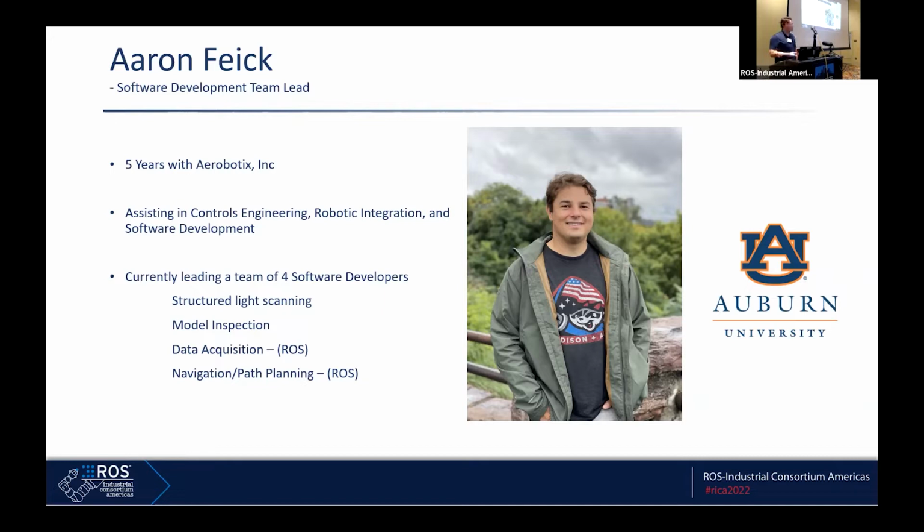Now that we're talking about software, Aerobotics has 4 different aspects of software that we really try to focus on. One is structured light scanning, so that metrology and inspection. We've developed our own software for a structured light scanner, so we can maintain our own integration of inspection. From that, we can get back model inspection data, so we can compare pre-paint, post-paint, pre-sanding, and post-sanding, and use that data to help tune the process. Sometimes our customers come to us without a process, and we need to help them discover the process for the paint or for how it needs to be finally tuned.